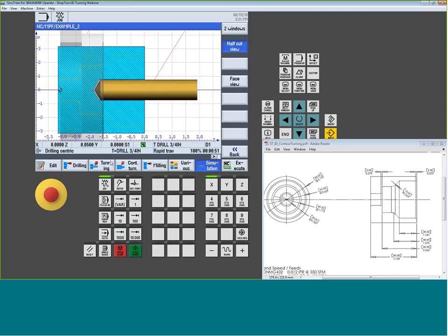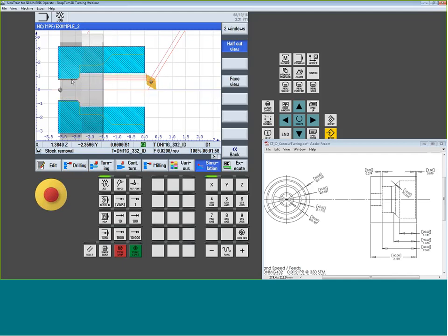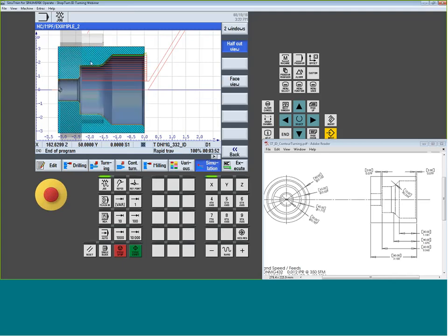And now we see we're drilling our hole. And watch the boring bar. So you notice how it never went into this hole. So you can really start to control the motion that you're getting just by understanding those little nuances of the cycle. So you notice it finished the hole. Finish cycle is always going to run every geometry point. But the roughing, it said, hey, you're not telling me I have any additional material on X, so why should I even go into that hole? If I had a pull-off here, then it would have gone into the hole. Because it would say, okay, well, my 0 is the end of the pull-off, but now I know there's material here because I'm using the shape to gauge where my stock is.